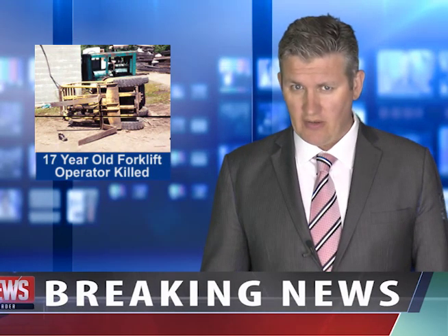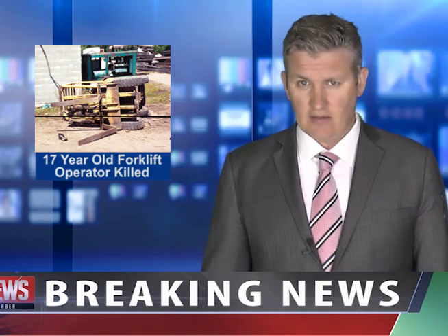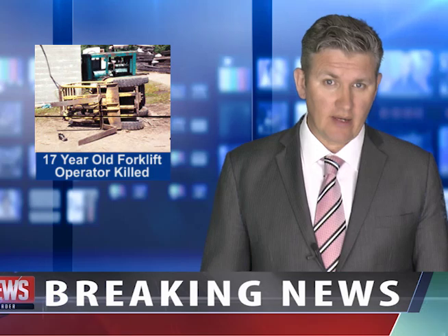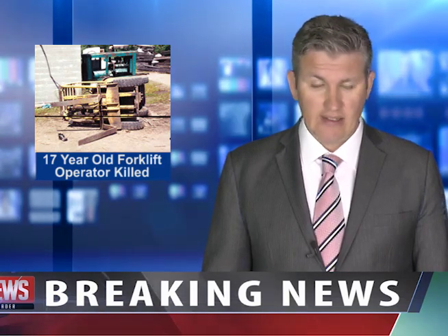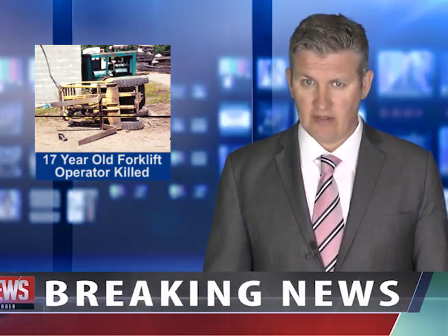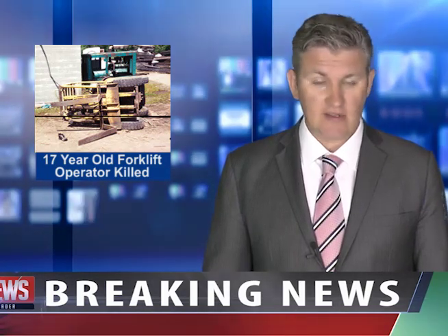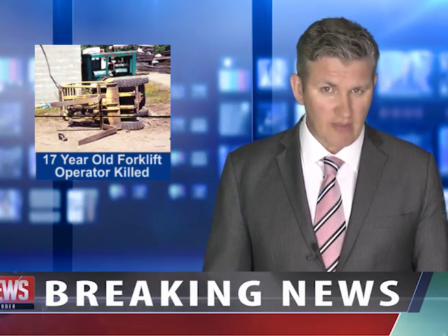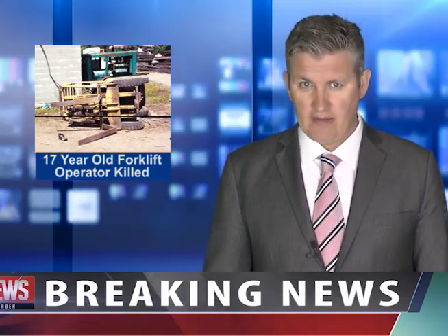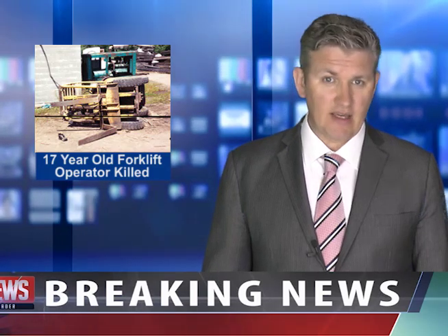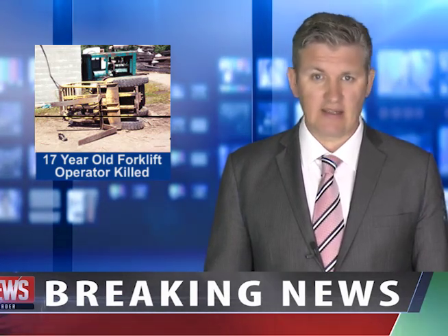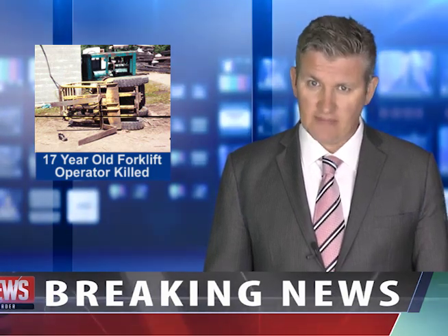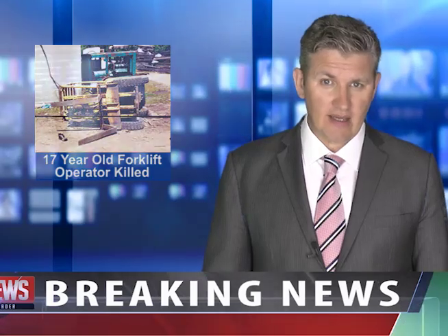And we've had an update on the cause of yesterday's fatality. The forklift operator lifted a pallet with 2 oil drums, but was unaware that one of the drums was empty. This made the load unstable and the vehicle tipped over when the operator tried to turn. Instead of staying seated and leaning away from the fall, he attempted to jump clear and was crushed by the overhead guard. Experts say you should always verify the stability of a load before lifting it, and always make turns slowly and carefully. A memorial service is being held on Friday.